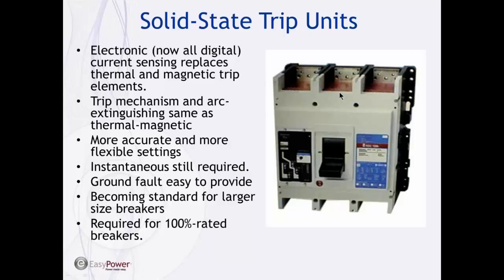All right, so we've been talking about thermal-magnetic type molded case breakers. And we're going to talk now a little bit about the solid-state trip units. So in what we call a solid-state trip unit, that bimetallic strip and that solenoid for instantaneous trip has been, for the most part, replaced nowadays with a digital microprocessor and current sensors. And so the waveform is sampled and digitized, and then there's some numeric processing that occurs, similar to the trip units on low voltage power circuit breakers or digital protective relays.